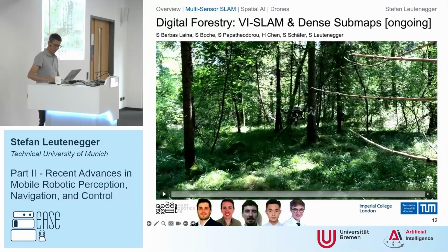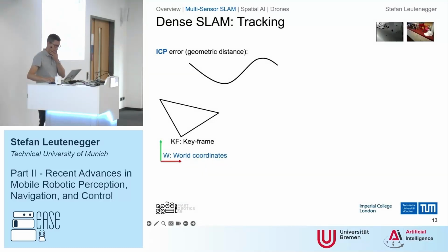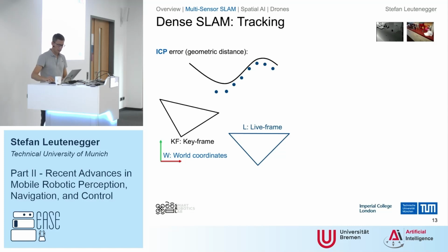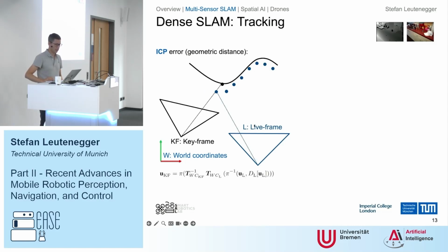Okay. All right. So then maybe I'll move to just one more little bit of theory that I haven't talked about, which is dense tracking. We can also try to align cameras with dense geometry. So far I've mostly talked about sparse. So what we do is ICP, for instance, with the depth camera, also with LiDARs, to try and align the back projected dense measurements here with, say, the projections in a keyframe.